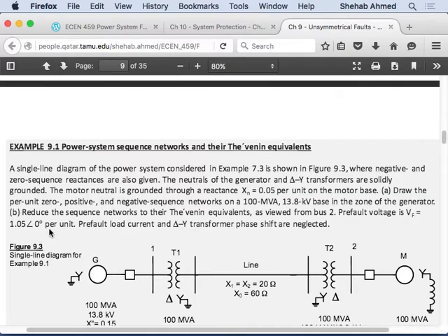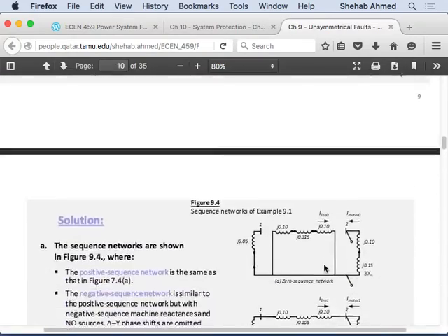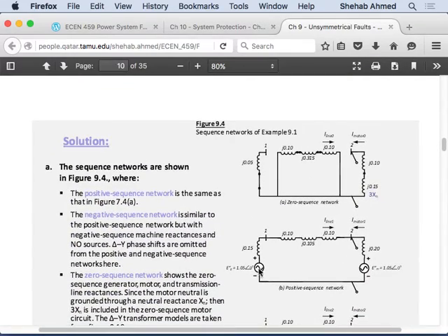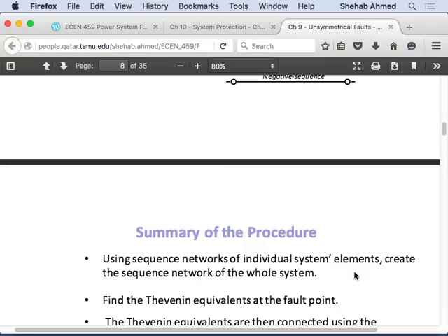They say the pre-fault voltage in general, right? So pre-fault voltage is the voltage basically in the positive sequence. It's 1.05 on the generator, but they need to be clear that there will be a pre-fault voltage on the motor side, because remember, if you go back to the induction motor representation in the sequence quantities, that's the previous chapter.